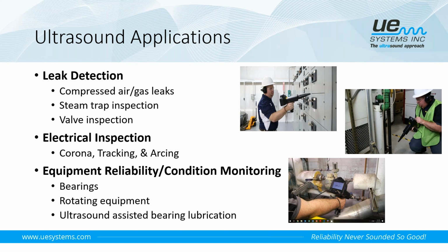You can also have leak detection, which would be a contact method. That would be steam trap inspections, to where we're listening to make sure that steam trap is operating the way that it should. With valves, we're listening for valves that may be in a leak by condition, or we're listening to see what that valve is doing. Is it open? Is it closed? Or is it leaking by?